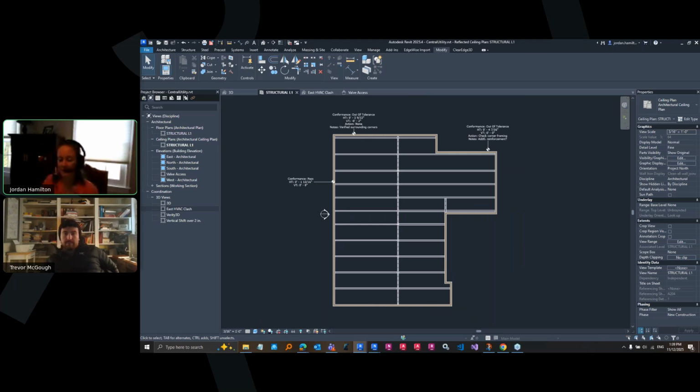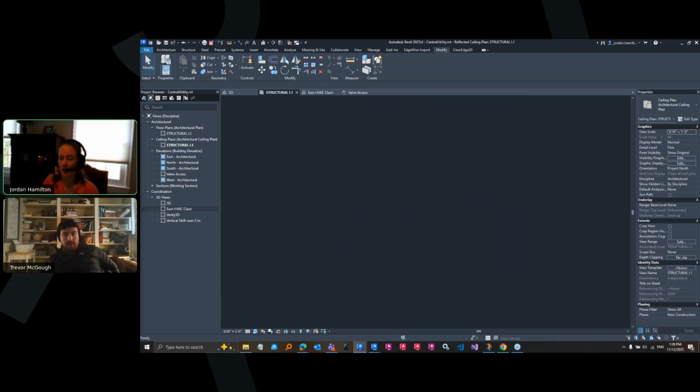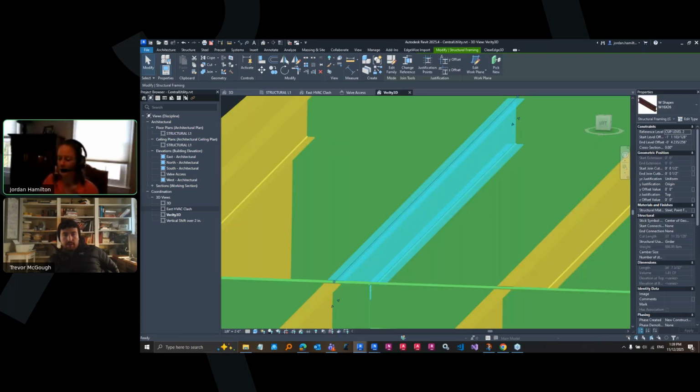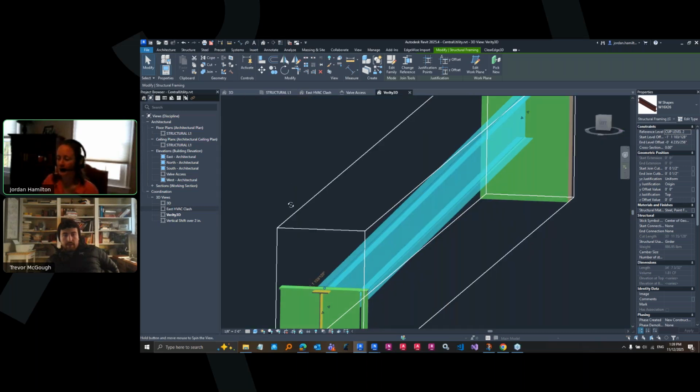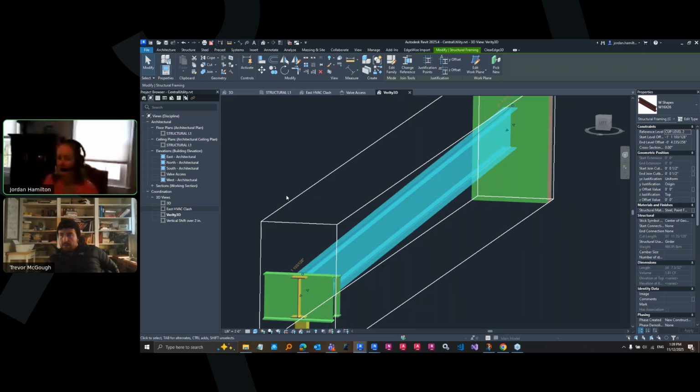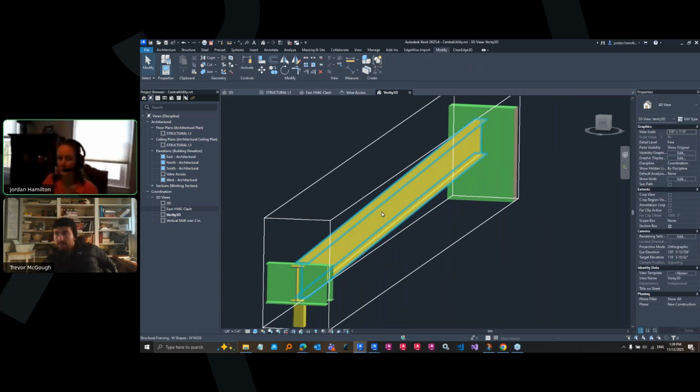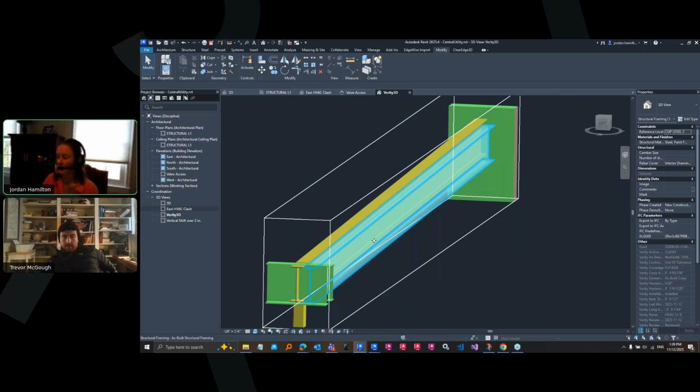In Revit, if we want to have the as-built location that Verity has found represented in the model, we can do so with an as-built copy of that object. So rather than moving your Revit modeled object and potentially breaking connected systems or doing something of the sort, we'll take this I-beam, for example. You'll click one button or one hotkey inside of Verity, and Verity will create that as-built copy of this item at the true fit that was found by the Verity analysis.